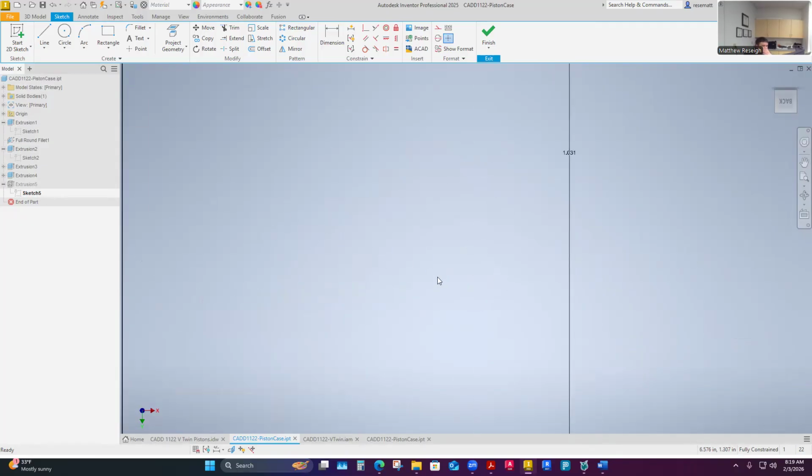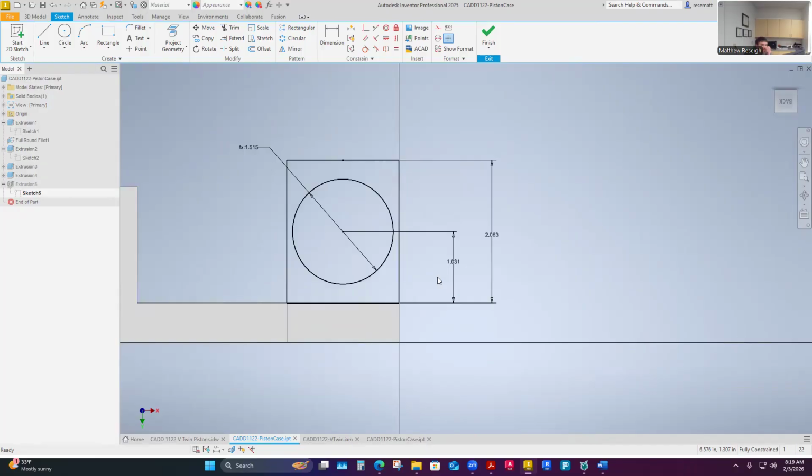And I think the other one that I said is definitely a critical dimension on this. I mean, they're all pretty critical, but the ones I definitely want to maybe change their precision of on my sheet would definitely be this, to show its full size. And potentially this one, even though this isn't the one that I've used on my sheet, this is the one that's controlling the height of that. So that's a 0.03125. I might want to just be aware that I need to probably carry this many decimal places to get this height correct in the assembly.